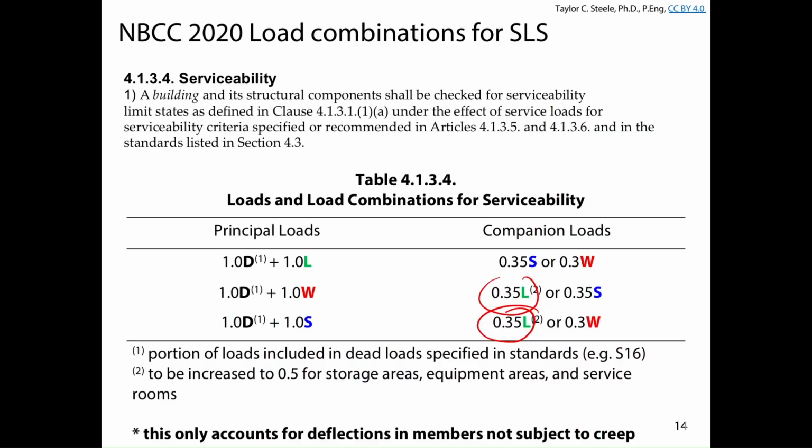So in terms of finished floor, the concrete's there, the plumbing, mechanical, electrical have probably already come in. They've installed their utilities for plumbing and for electrical systems, lighting, etc. And then they put the floor down, right? So the finished floor is one of the last things that gets installed. And it depends on whether or not that's installed before or after the partitions. If you've got cubicles, for example, then you're going to install the partitions on top of the floor system. But if you're building in fixed partition walls, like stud walls or masonry walls, then the flooring is going to come after. So basically, you're going to have the steel structure itself, concrete, all the other stuff.